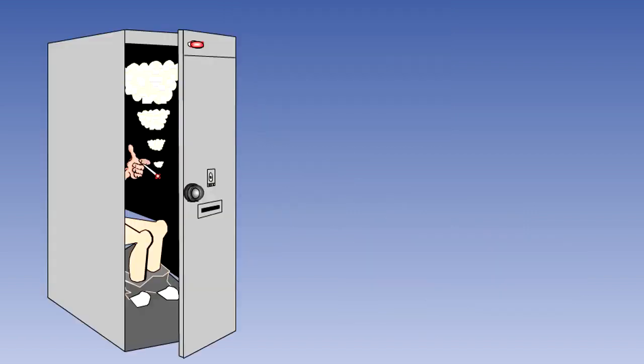It is a regulatory requirement that on aeroplanes with a passenger capacity of 20 or more, each lavatory must be equipped with a smoke detector system or an approved equivalent that provides a warning light in the cockpit or provides a warning light or audible warning in the passenger cabin that will be readily detected by a cabin crew member.